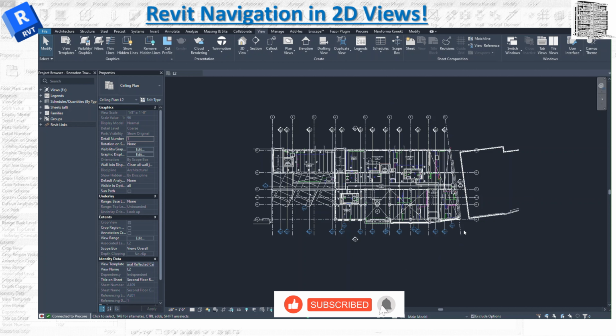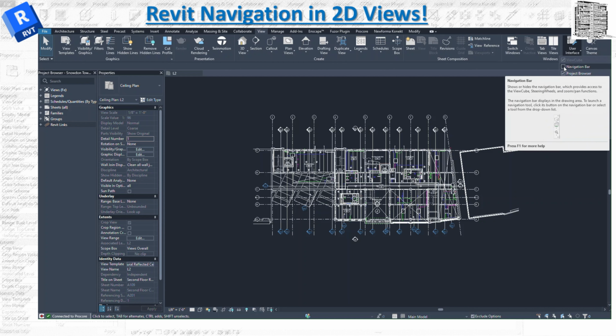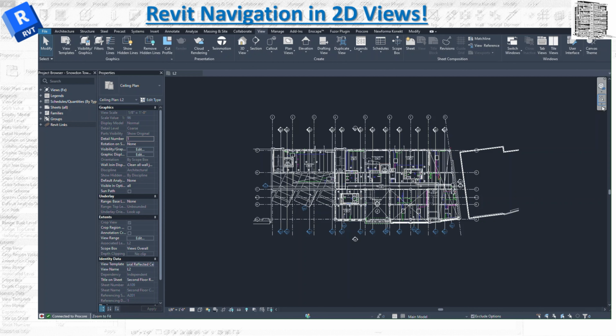The first one: when you open up the 2D sheets or the 2D view, you can see the panel right there. It has the zoom button and also the steering wheel. If by any accidental removal this one is gone and you're looking to find it, you need to go to View, all the way to the Windows user interface, and you can see right here the navigation bar. When you click on this one, the 2D shows up, and when you go to the 3D views, that navigation turns into 3D.